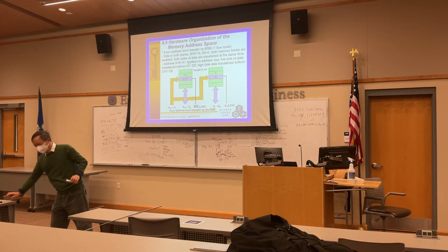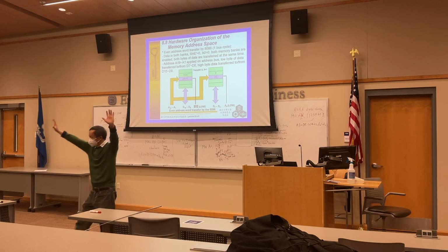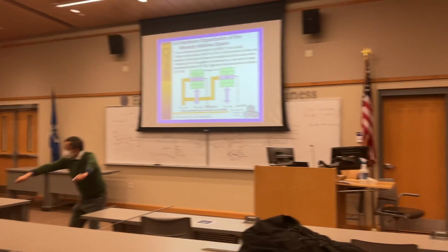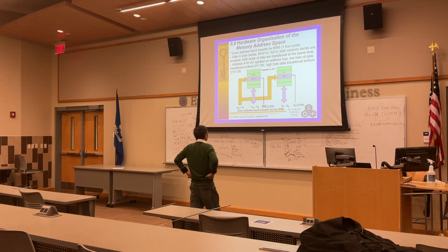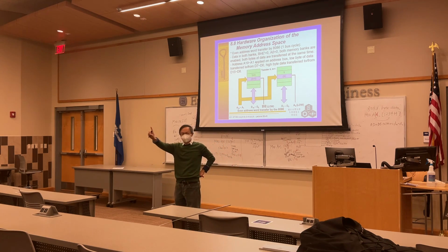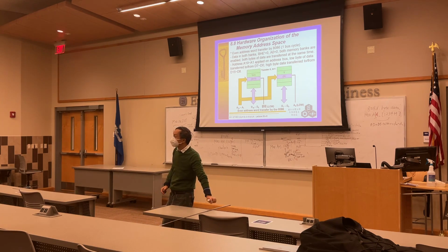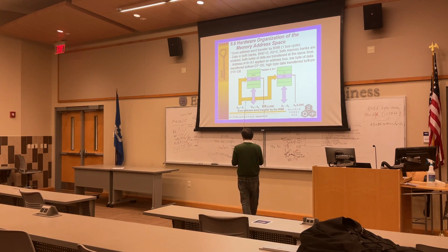I have two hands: lower bank and higher bank, I can hit them both. Go to the AX register. How many bus cycles? Only one bus cycle, because they are aligned. Our data bus is also simplified. So what happens is we calculate the physical address. It's one bus cycle.